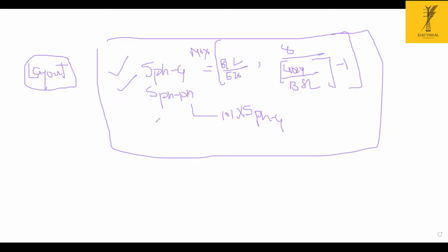Generally, the clearance required from the ground depends on factors like the voltage class, height of the person, height of the footings, and depth of snow, all these things, right? I also have to consider clearances with respect to vehicle movement in the substation, and check clearances with respect to the fences, substation buildings, or working clearances.